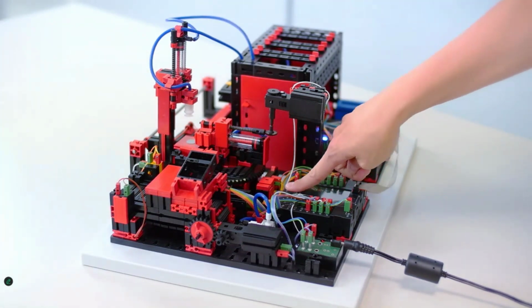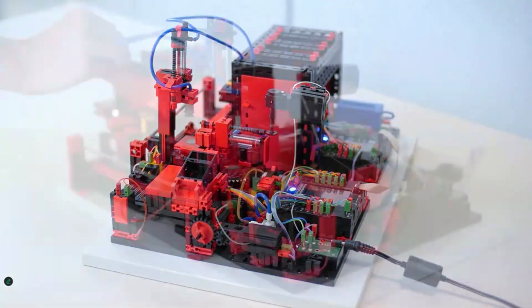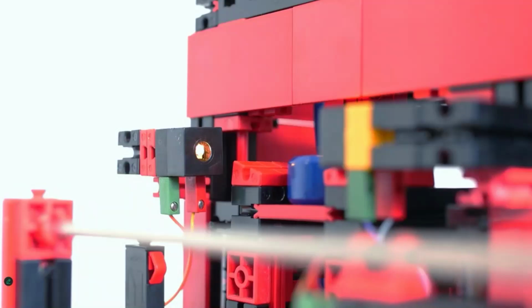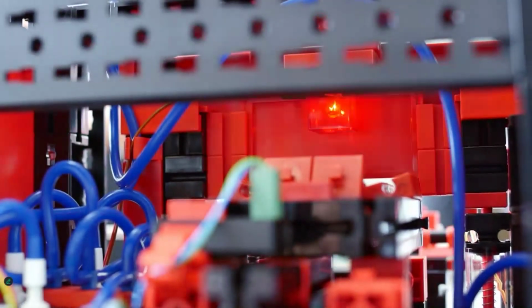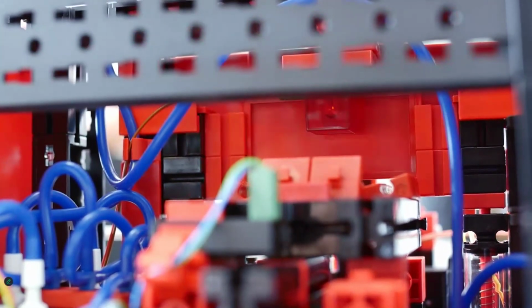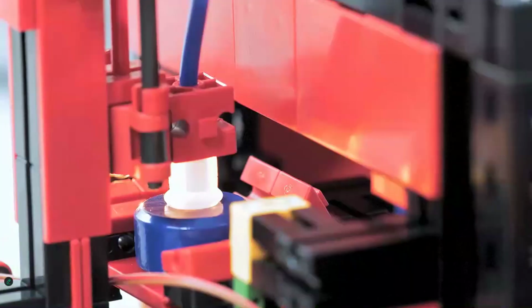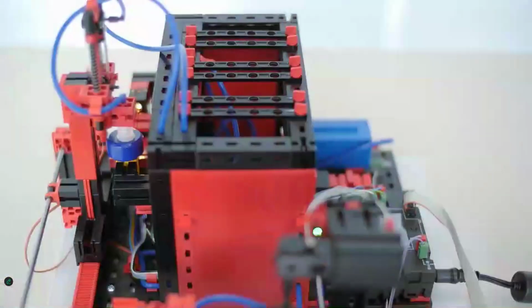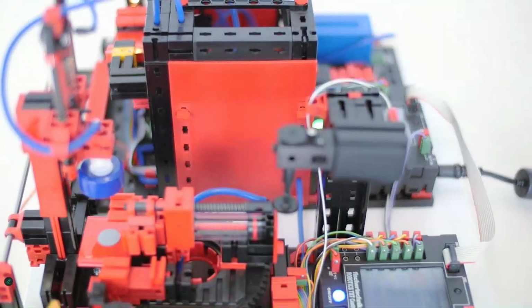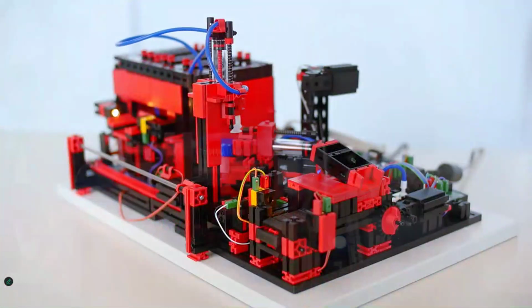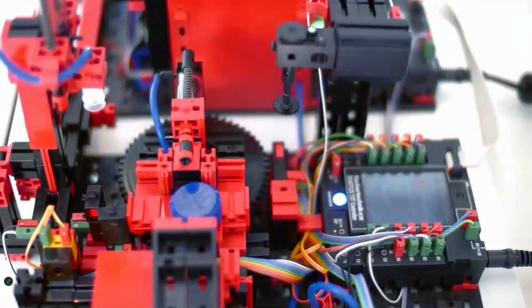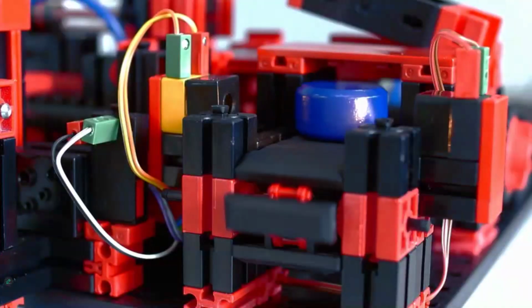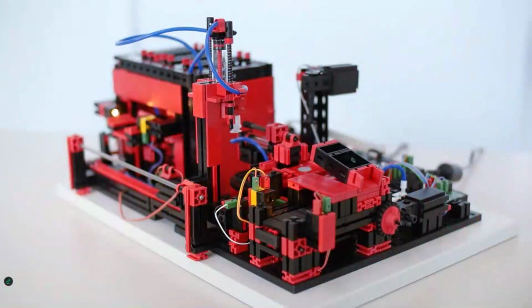The dimensions for the model are approximately 20 by 14 by 12 inches. It has a weight of about 11 pounds. Again, it's available in both a 24-volt version for use with the PLC of your choice, with once again, relay board for motor polarity reversal, and both multi-pin connector, 34 pins with a grid of 2.54 millimeters, as well as additional PCB terminals with push-in connections for all inputs and outputs. And the 9-volt version, in this case, is connected to two robotics T controllers. So, of course, two power adapters would be required for all operations.